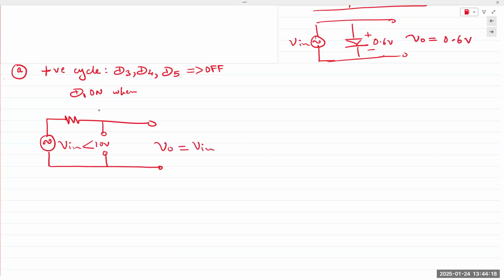Again, the shape doesn't matter. Yes. Good question. So instead of an ideal diode, I'm analyzing it as a regular diode. If it was an ideal diode, I would simply say the diode is a short, 9.4 volts at the output.